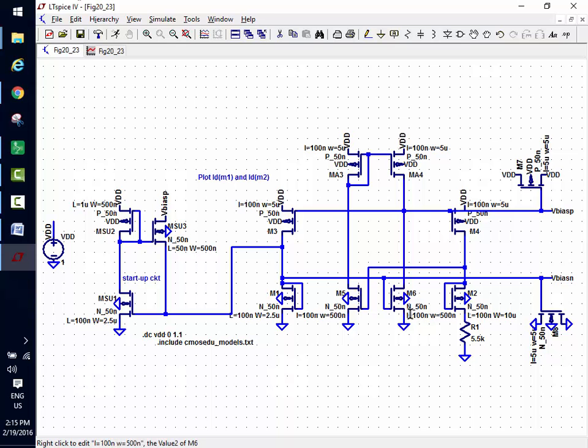All right. What is this transistor? Where's the only high impedance node? Meaning only gates and drains connected to it. This one right here. And so later in the semester, we're going to cover stabilizing, and the way I stabilize this is I put a big capacitor to ground, and this way I put the big capacitor to VDD, so if I have noise on VDD, it feeds into this voltage to keep ideally the source to gate voltage constant. Okay, we'll cover all of these things in more detail.